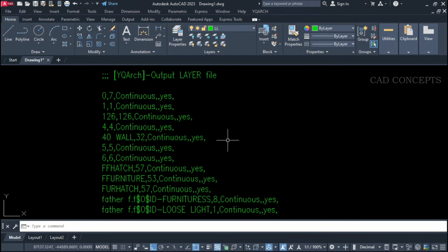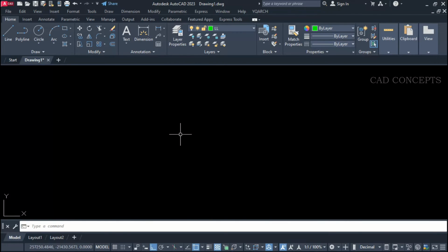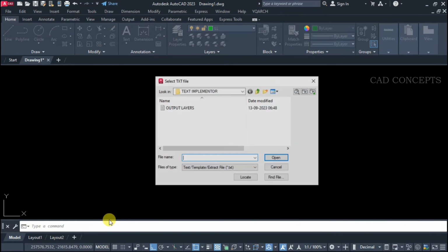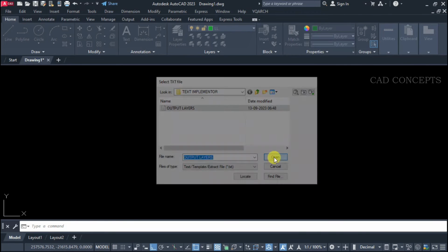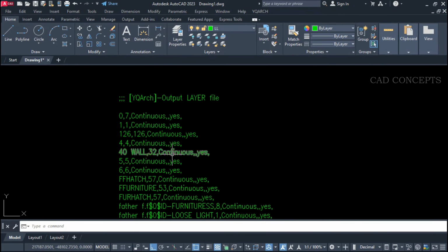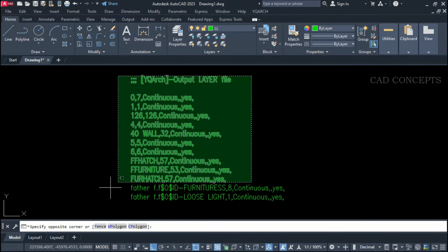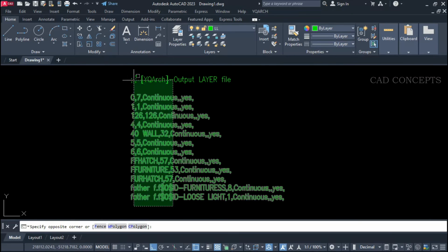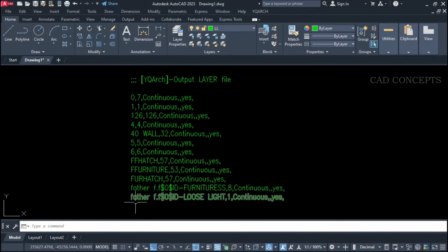You see here, this way directly you can place your output text in AutoCAD simply. Same as this, CTT command. Locate your file and provide scale. You are getting it properly in one time. You can provide angle also. So multiple text you have and you want to insert, you can insert this way at a time.